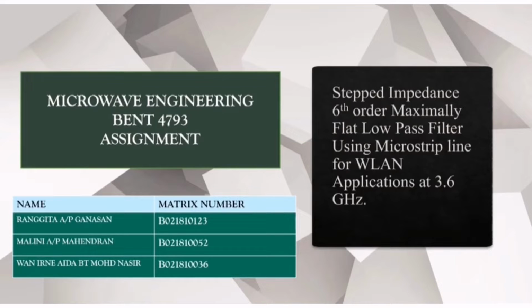My name is Malini and my groupmates are Ranggita and Irne Aida. In this video, we'll be explaining and discussing our assignment, which is a stepped impedance 6th order maximally flat low pass filter using microstrip line for WLAN application at 3.6 GHz.